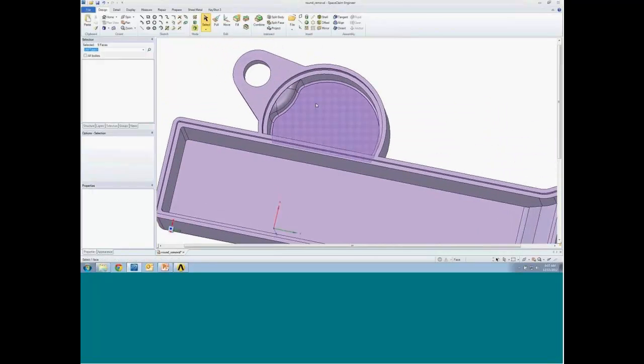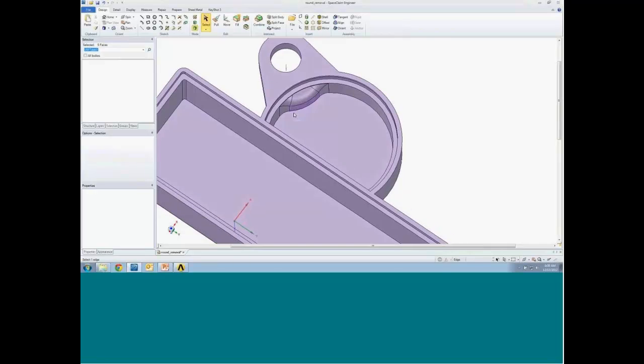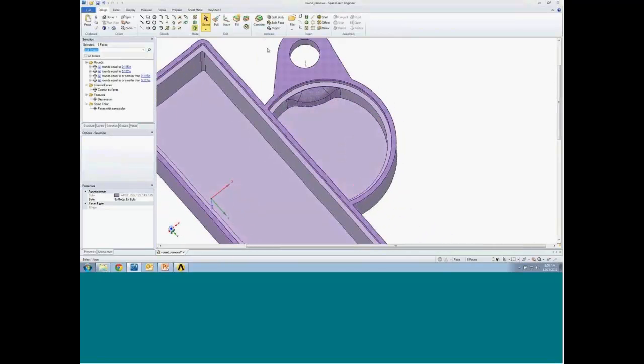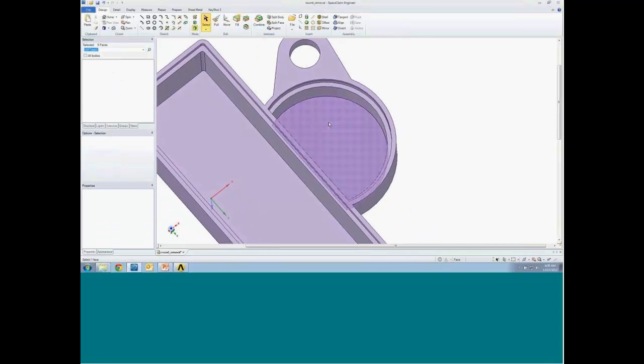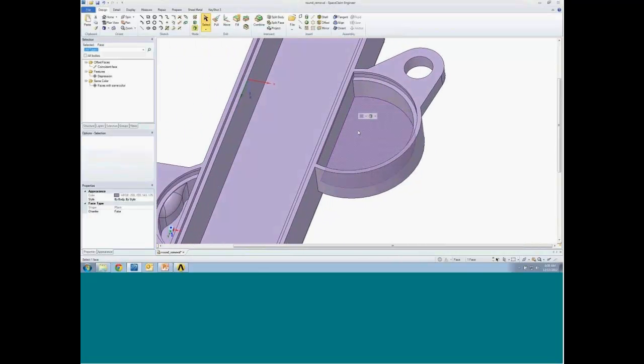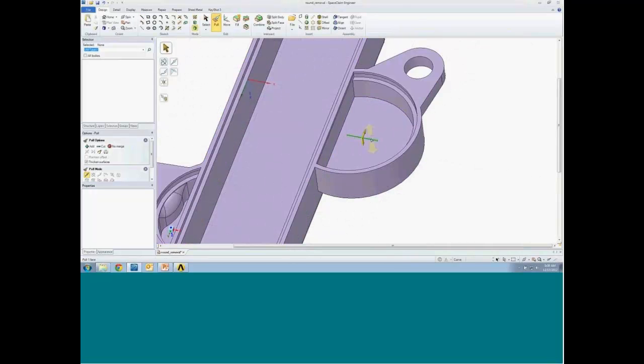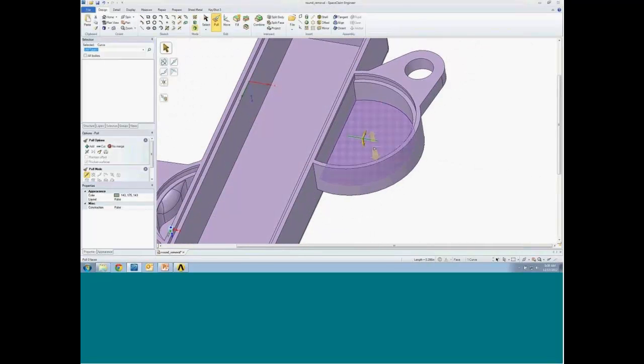Let's do the same thing on this protrusion sticking on the outside. I may like to go ahead and get rid of those rounds that were at one time selected, and then this small little bump, fill that in. Because maybe what I end up testing this out, I find out I may need to put a rib in here to add some additional support. And maybe you just want to play the what-if scenario and see what happens if you add some kind of geometry somewhere, and see if it enables you to get to the results you're looking for. Well, it's so easy to do in SCDM.